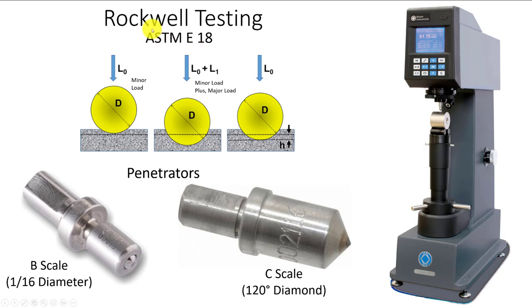Let's keep on this rather smartly here. We have a Rockwell testing. This is our machine in lab. We have a round part. We have the correct anvil in, taking a hardness. So we're going to have to do a roundness correction factor on that.